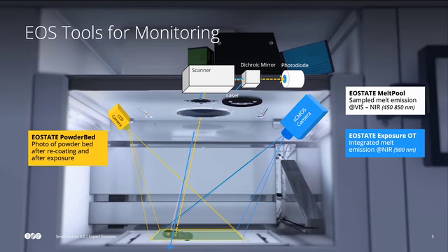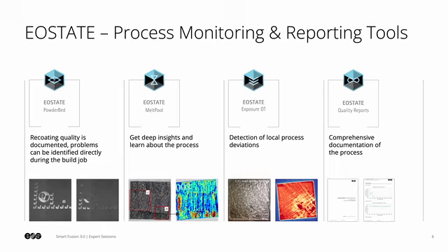The scene now belongs to the scanner-controlled lasers, protective gas flow, powder, solidified material, and also monitoring sensors such as oxygen sensor or AconitySTUDIO exposure OT camera. We are strongly committed to understand, monitor, and optimize the complex interplay between process parameters and part quality by keeping an eye on productivity and sustainability.